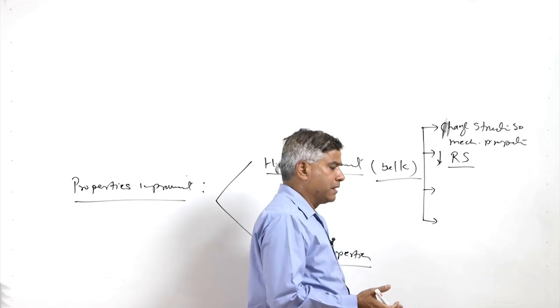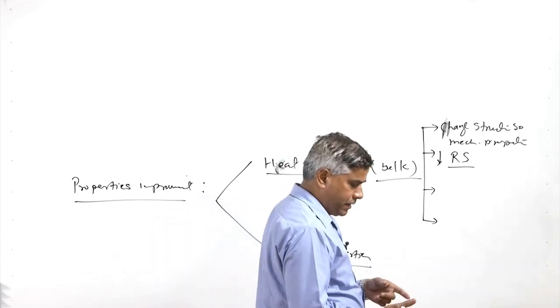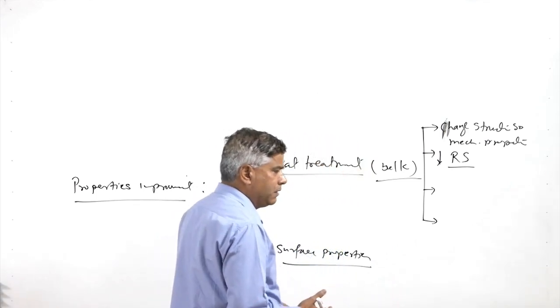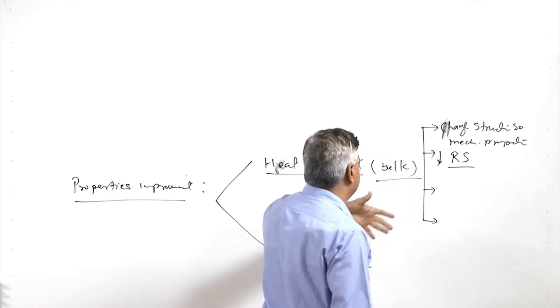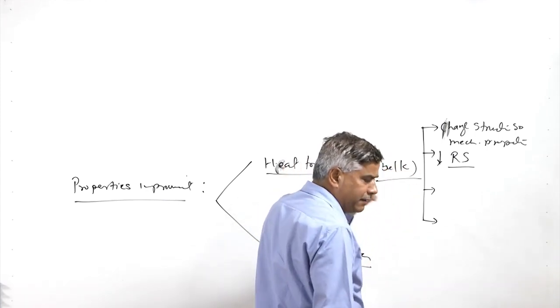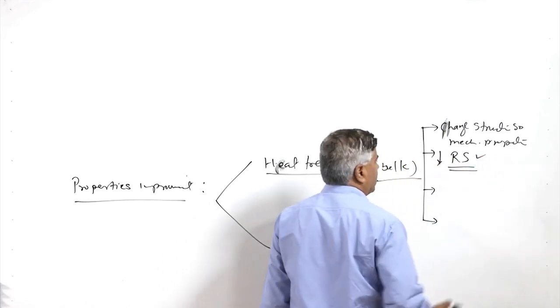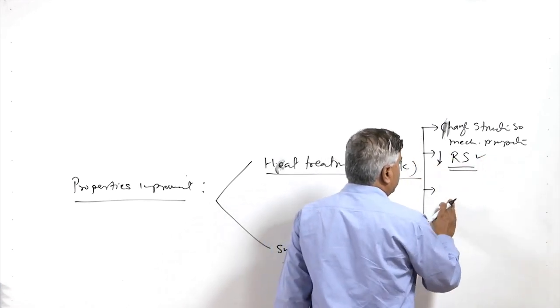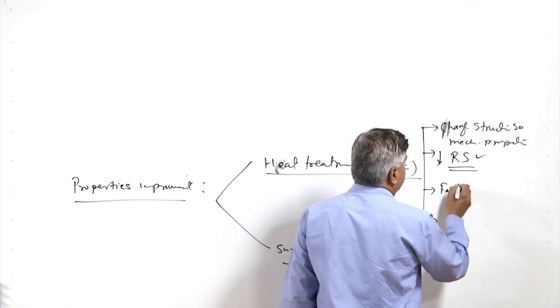Say it is either the heat treatment, or the casting, or the machining, or the welding. In all those cases, if residual stresses are developed, they will degrade the mechanical performance of the components. So we want the residual stresses to be relieved. Then it is also done to facilitate